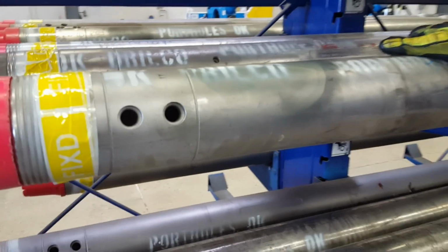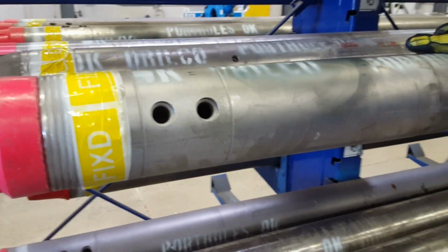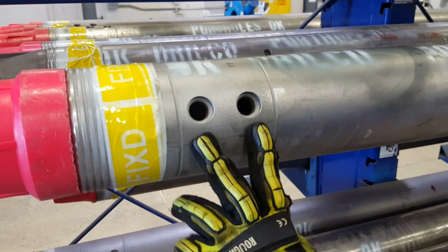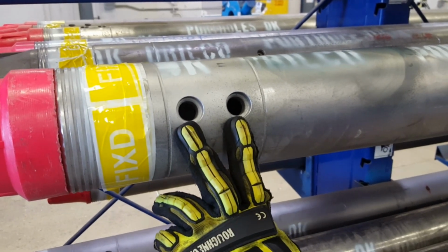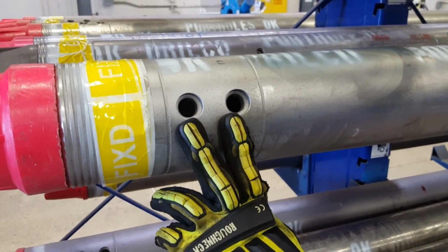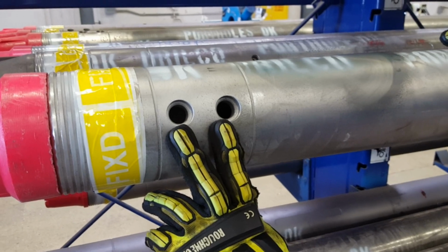So a 475 collar is slightly different. This is a 475 stabilized collar. These are the anchor bolts. This is the ABFT design, which is a slightly bigger bolt than the old version. You should only see these big bolts on collars. Let somebody know if you see a bolt that's smaller than this.